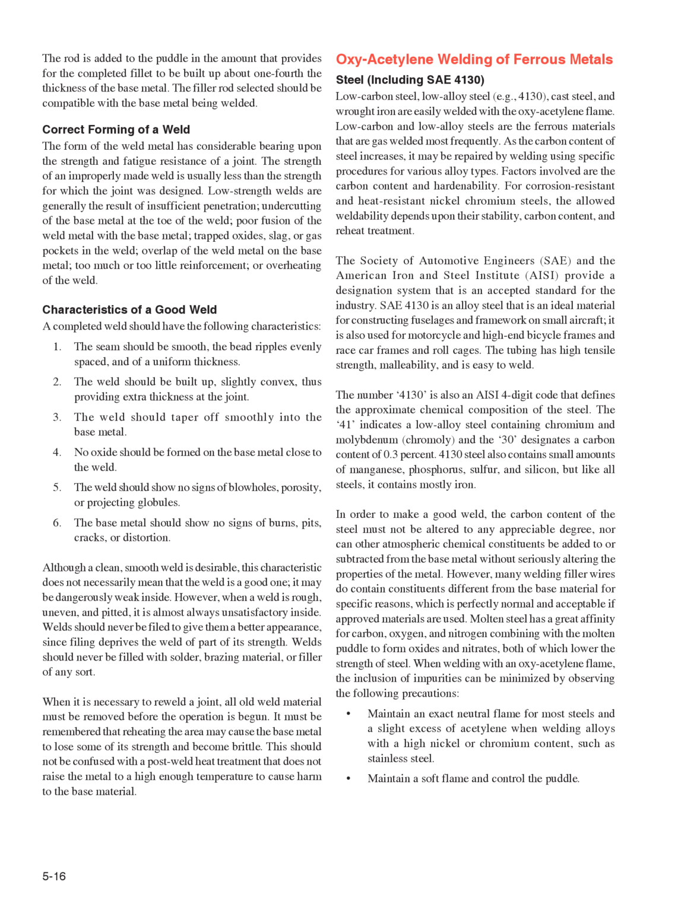Low-strength welds are generally the result of insufficient penetration, undercutting of the base metal at the toe of the weld, poor fusion of the weld metal with the base metal, trapped oxides, slag, or gas pockets in the weld, overlap of the weld metal on the base metal, too much or too little reinforcement, or overheating of the weld. Characteristics of a good weld.